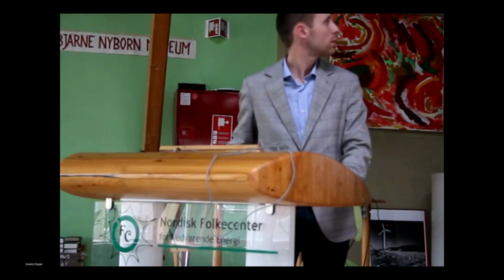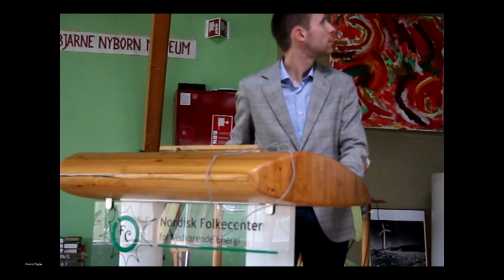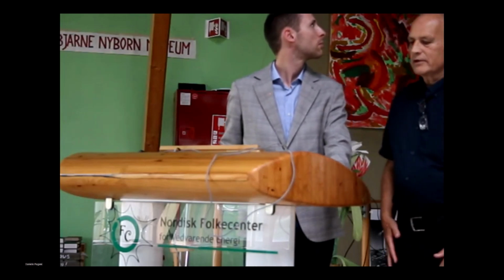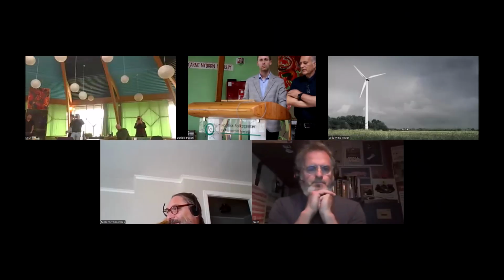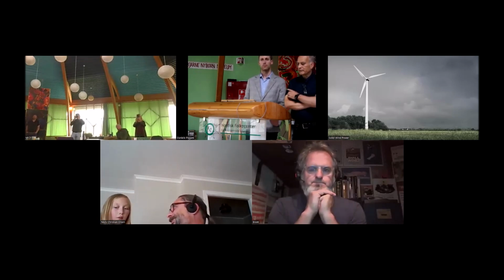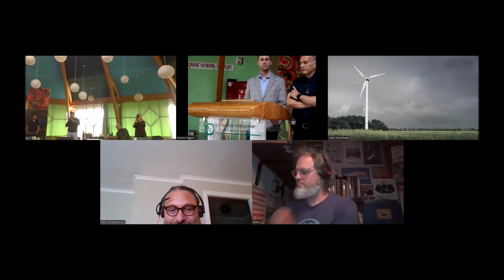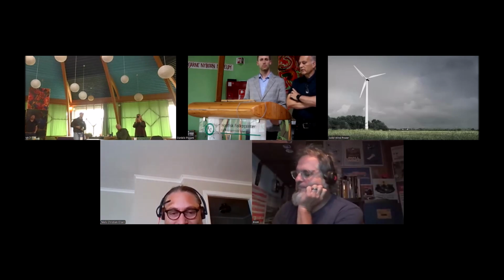Okay. Sorry, quick question. What's the largest power rating that Voltsys is currently working with for wind turbines? Was it 10 kilowatts? I forgot. Well, typically we work on up to 30 kilowatts with standard products. If we get above 30 kilowatts, we can use 3 controllers. Putting rectifiers in one instead of using a 3-phase rectifier, we use one diode for each controller to control, because if you put rectifiers in parallel, they don't work in parallel. But so 100 kilowatts is the largest project we've done so far. That's in Korea.